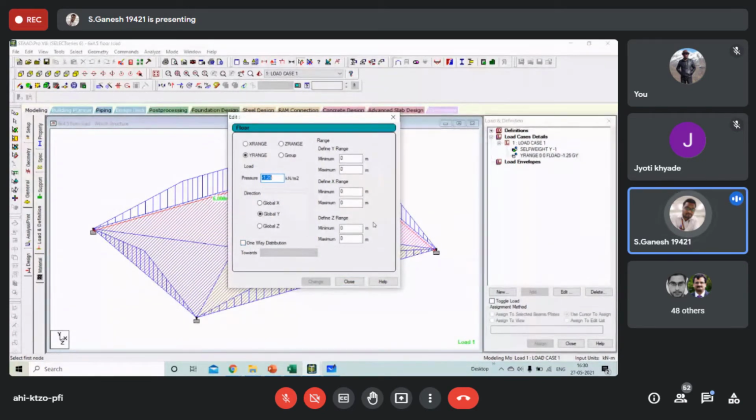Wherever you studied one-way slabs, where the one-way slabs are to be done, basically another note: where can you see the application of one-way slabs? One-way slab application is highly seen in cantilever portions, in the balcony area of a residential building. The second application is in the staircase. Wherever the staircase slabs are coming, the soffit slab, S-O-F-F-I-T, we have the one-way slab distributions.